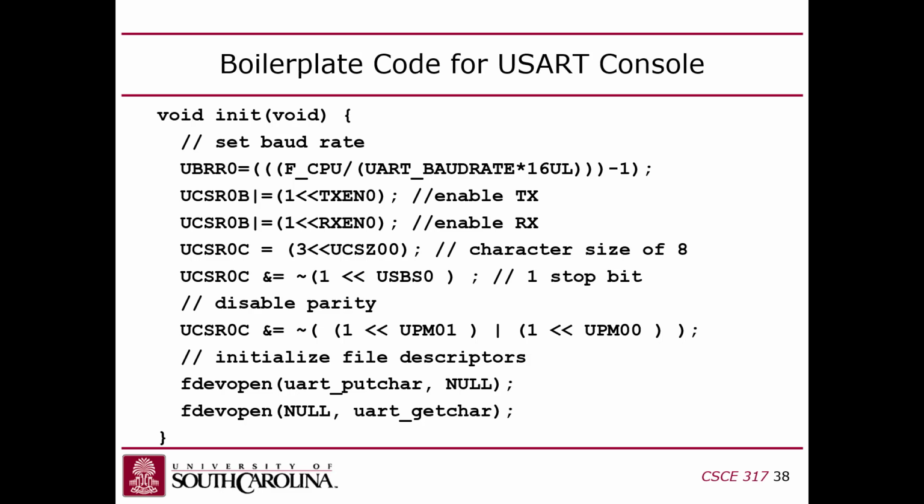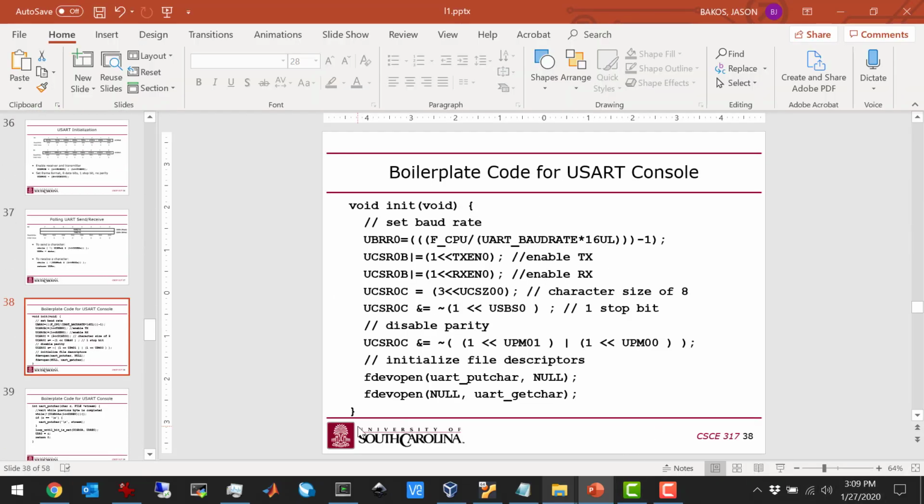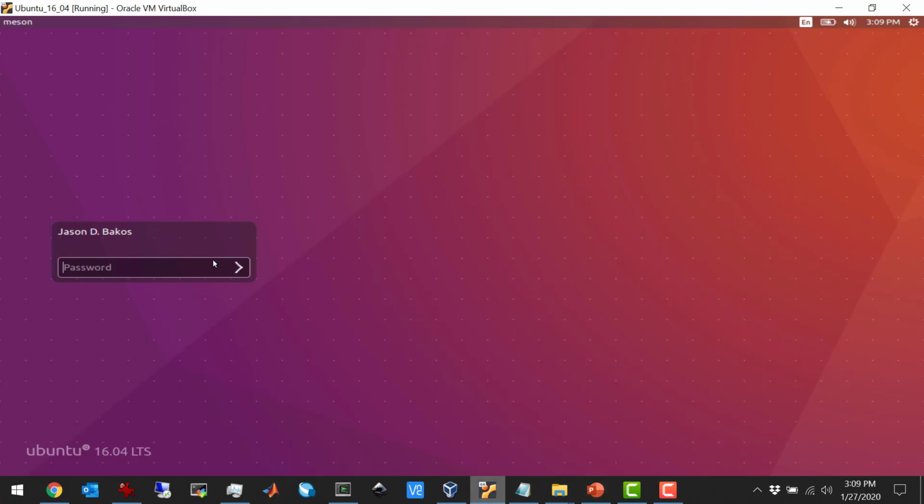If you search for AVR libc fdevopen, they have docs online, and depending on how the version of Ubuntu in the university labs handles their packaging, if you do man and then the name of the AVR libc function, it should give you the man page for the AVR libc version of that function rather than the POSIX version. That seems to be something that's dependent on how they decided to package stuff, though. Okay, he can check.